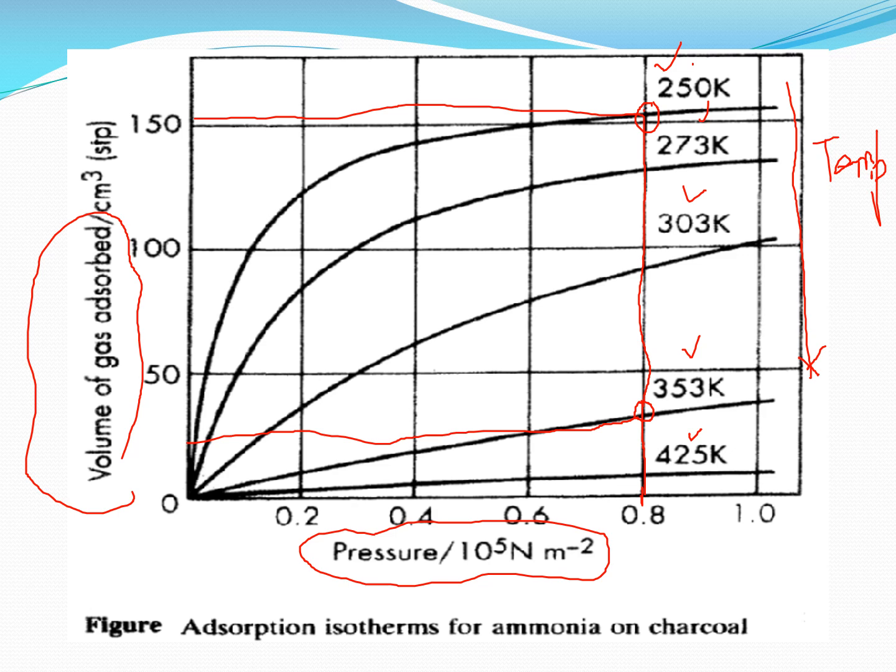That means at low temperature we have high adsorption, and as we increase the temperature, the adsorption becomes minimized. We know that as we increase the temperature, the kinetic energy of the molecules increases. The molecules tend to move faster, and rather than being retained on the adsorption column or onto the adsorbents, they tend to move away and exit from the column. So if you want adsorption, you must consider the temperature and have a certain optimum temperature, at the lower range. Very low temperatures, like 273 K, which is 0 degrees Celsius, or 30 degrees Celsius, even minus temperatures in degrees Celsius.